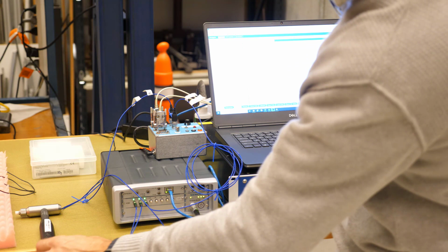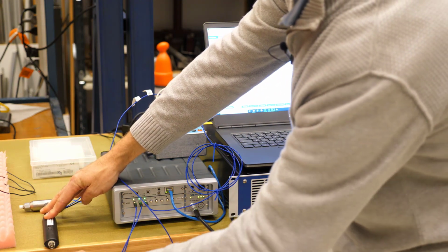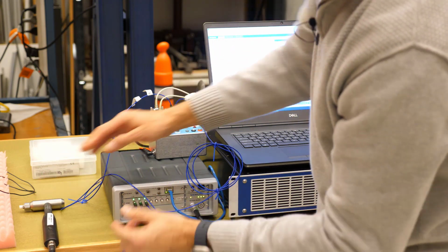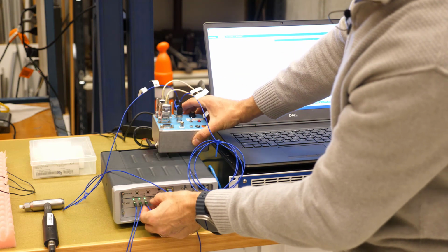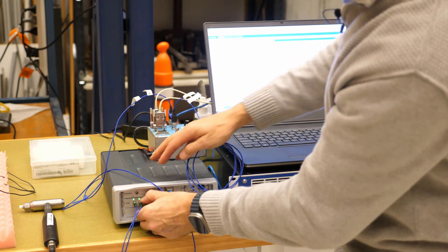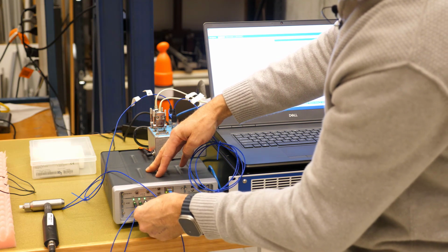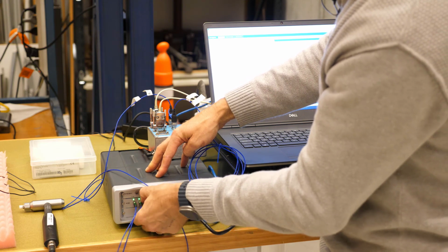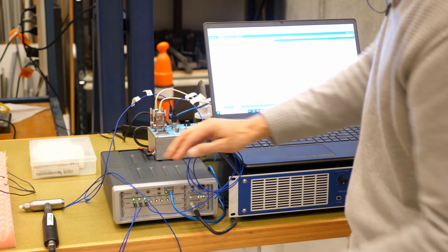This device is IEPE, ICP, so if I remove the cable, it recognises there's no sensor attached, goes short circuit, I get a red light. When I reconnect it, I get a green light. These 2 channels have been conditioned externally. These green indicators don't tell me whether or not I'm closed circuit or not, they're just expecting a voltage. So there is a little bit of capability, intelligence built into the acquisition system, particularly with integrated electronics, piezoelectric.